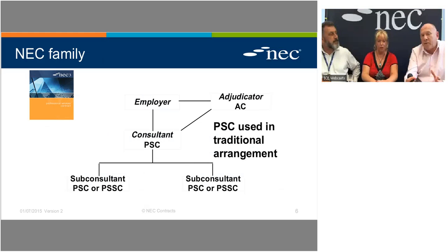So if you are a designer, what are the different forms of NEC contract that may come your way? The classic appointment is between somebody called an employer, client if you like, and somebody called a consultant, and they will use the top left orange book contract there, the professional services contract. Sometimes they may sub-consult, sometimes they may just carry out the services themselves. There's an adjudicator top right. Hopefully you never fall out and have a dispute heard in adjudication, but that provision is there just in case. So the classic engagement of somebody to provide design is via the professional services contract, directly between an employer and a consultant.